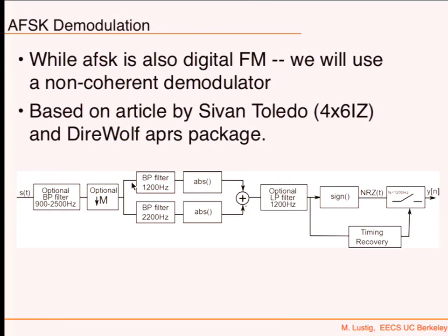Okay, so now it's an NRZ signal. It goes from -1 to 1, -1 to 1, right? And it switches. And what I need to do then is sample, because I need to get my bits out. And where do I sample? I need to sample in the middle of my bit length, because that's when you do the match filtering. That's where the maximum happens, okay? In the middle. If you don't sample in the middle, you're going to be compromising your signal-to-noise ratio, because you're going to have a lower value, and so noise can throw you off to be negative. But in the middle, that's the best one. Okay? So we have to sample in the middle of the bit length, all the time.